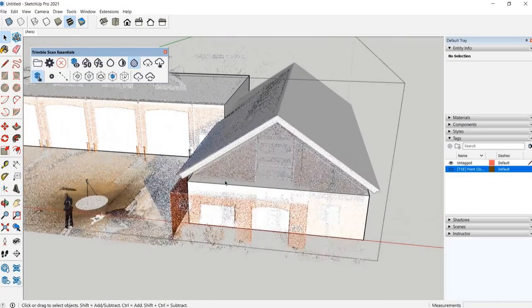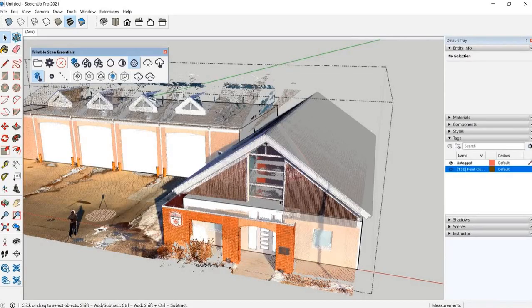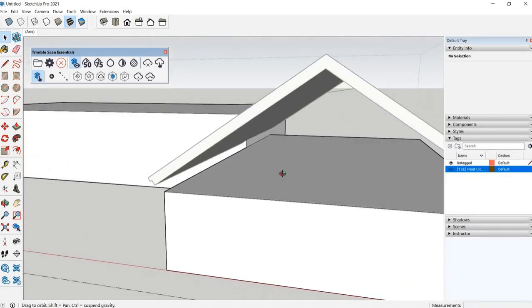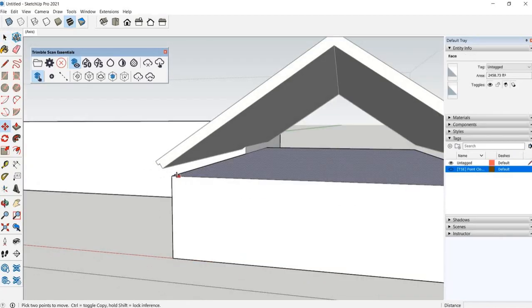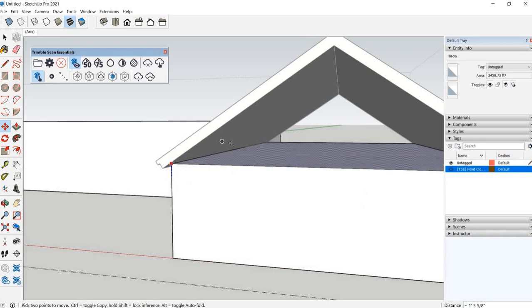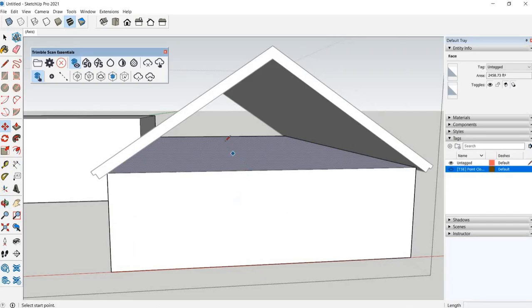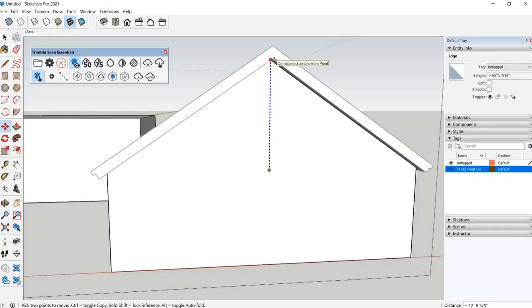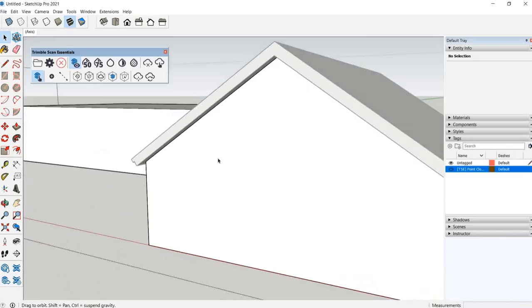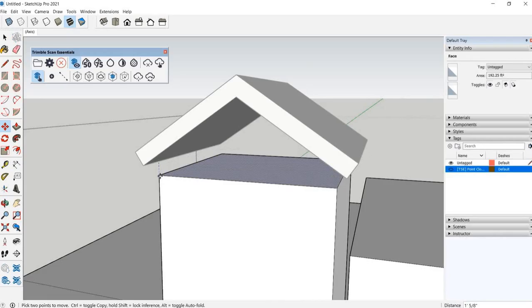By the way, because we've been good about aligning our SketchUp geometry properly, it should be fairly easy now to edit our buildings group, select this top surface, move by this endpoint and lock it to the blue direction and match it up exactly with the roof surface. Then we can draw an edge from midpoint to midpoint and move that edge straight up to exactly meet the roof we created. And I'll do this for the tower roof as well.